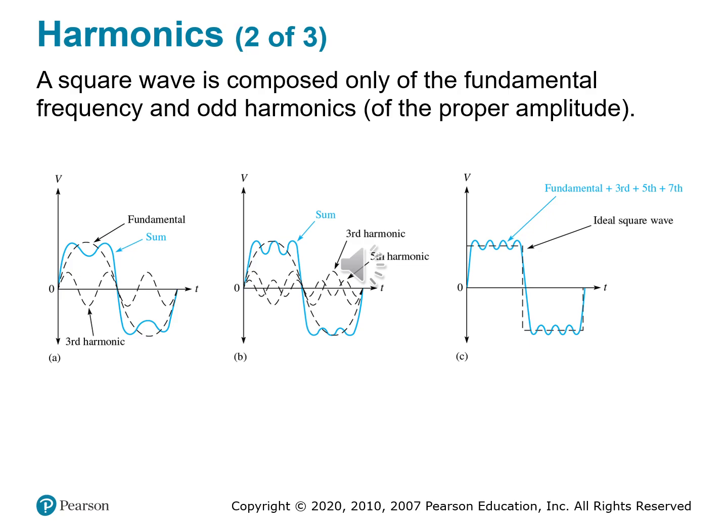You move one step further, like in panel C, where you're adding the seventh harmonic, right? And what does that result in? A waveform that closely resembles an ideal square wave, with flat tops and steep transitions, though you'll notice a little ripple on top of each harmonic.